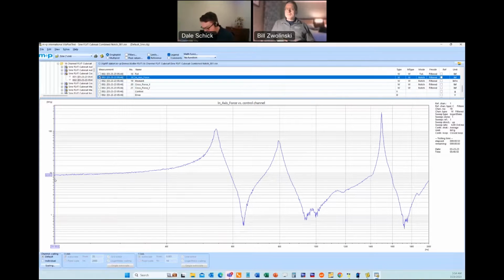So if this is a 4 kilonewton sensor, for instance, that I'm using here, and I have about 8 kilonewton range in the force Z before I preload it, once I preload it, I only have as much headroom as I have actually preloaded. I needed to take a look at this at the low frequencies, do the transfer function from a low-level input, and then adjust the sensitivities accordingly to include the force ring, the unit, the cabling, the hardware, and everything. I use all those in the calculation to determine the sensitivity.